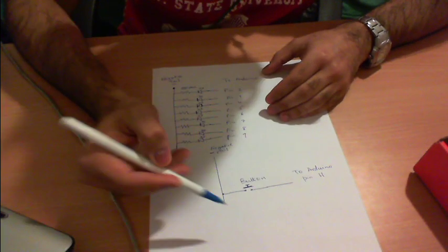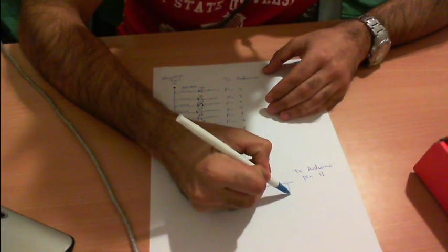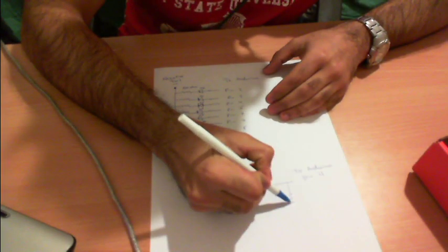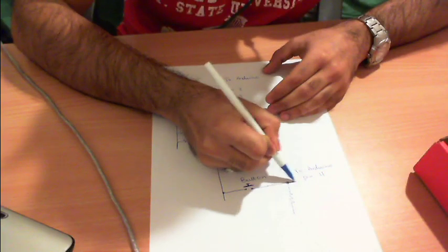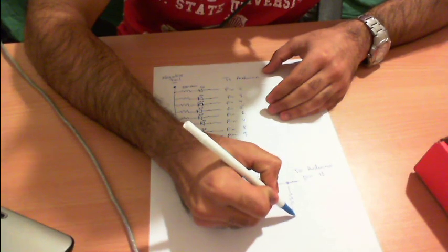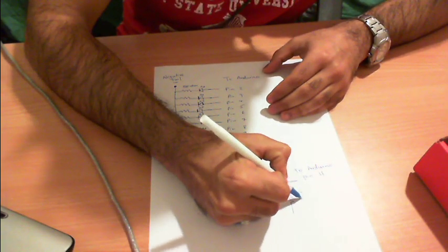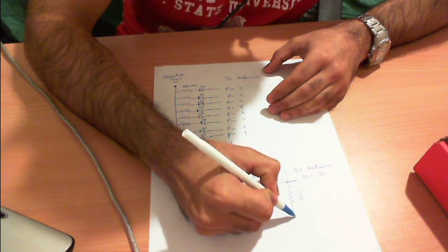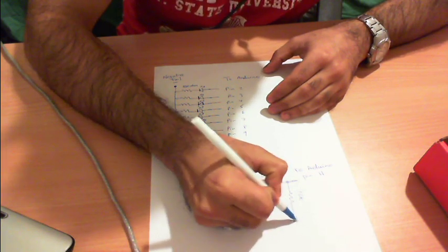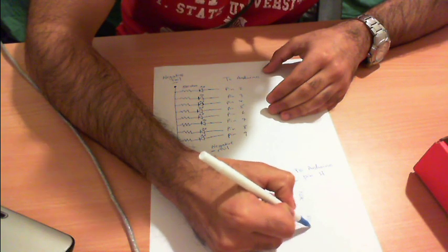So what we need to do is we need to get a 10 kilo ohm resistor, and we need to attach that to this junction here, so going to pin 11 as well, and then we need to connect the other side of the resistor, so that's 10k, and the other side needs to go to the positive rail, so positive.